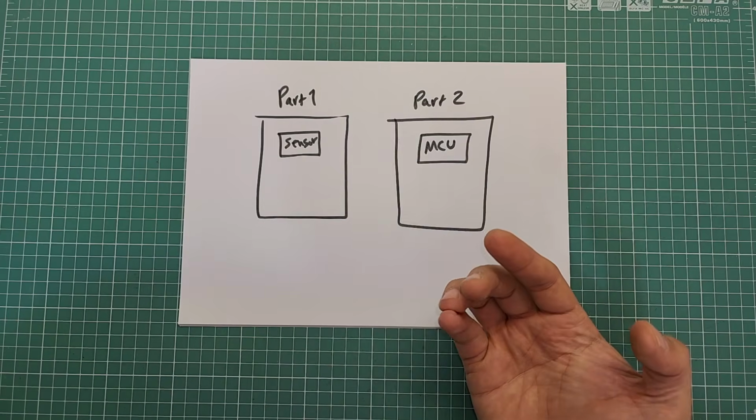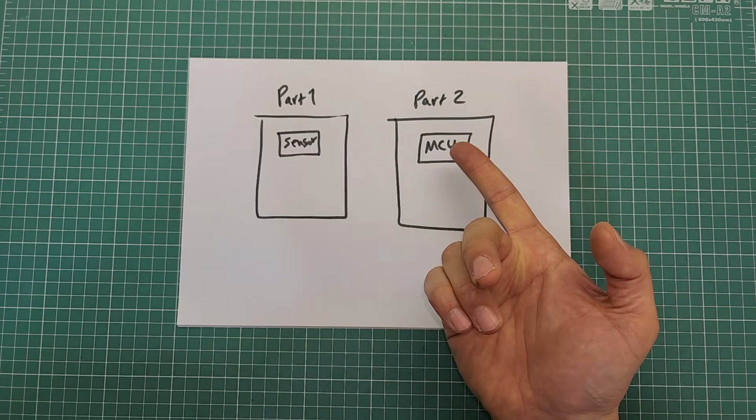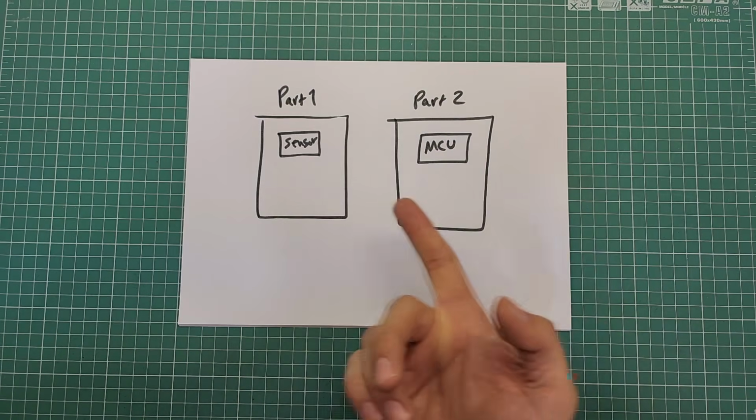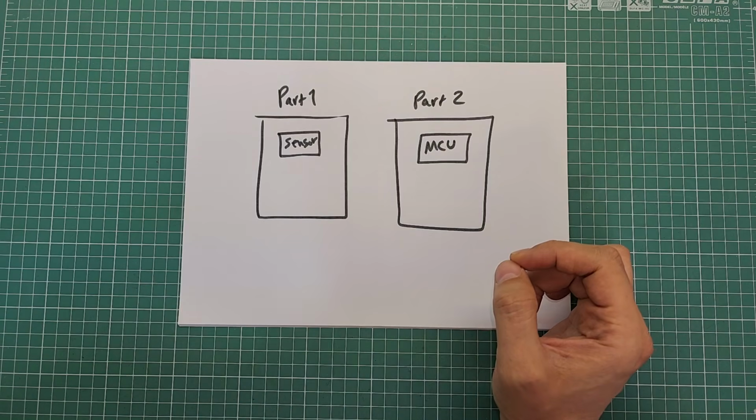In a normal situation, it's easy. We just need to connect the sensor output voltage to ADC on the microcontroller and grounds on both sides together, and then it's okay for the microcontroller to read the sensor value. It will be okay, but what if the distance between these two parts is very far? Say 2 miles, for example. Is it okay to use analog voltage to transfer sensor value to microcontroller? Absolutely not. The resistance of long wires will affect the sensor value. It will reduce the sensor voltage.